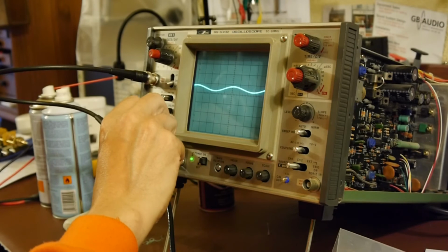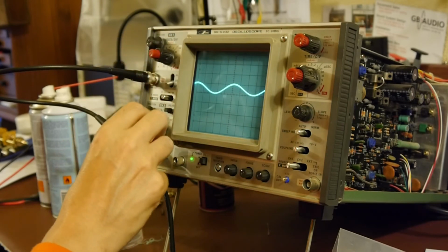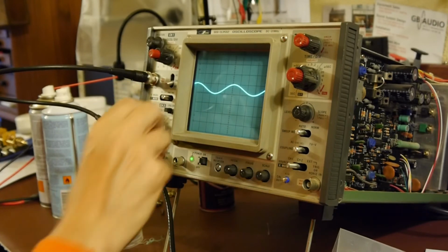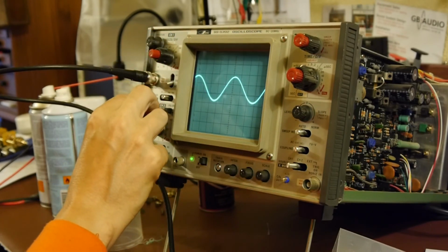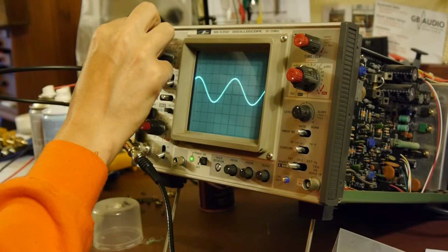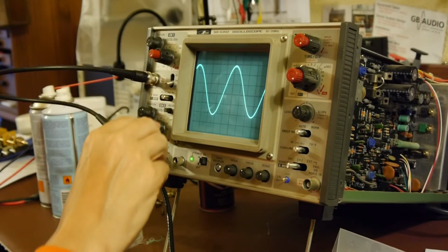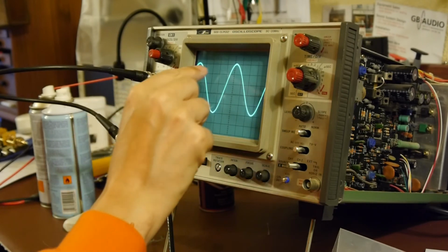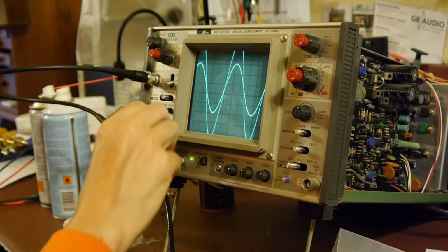So let's go to 5 volts per division, so that should then occupy 1 full trace, and approximately it does. Yeah, they're fine. 2 volts per division. There should be 2.5 divisions on here now. So let's just line that up. Line that one up. Yeah, just over 2.5 divisions, so that's looking good. Let's go to 1 volt. We should have 5 divisions now. Just line that one up. 1, 2, 3, 4, 5. Yep, 5 divisions. So go to 0.5 and we're going to go off screen now.